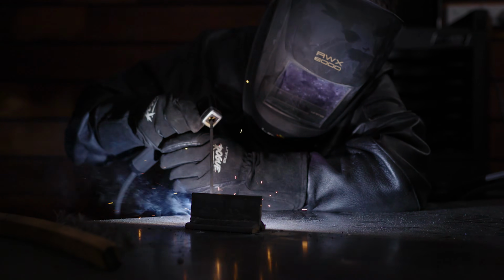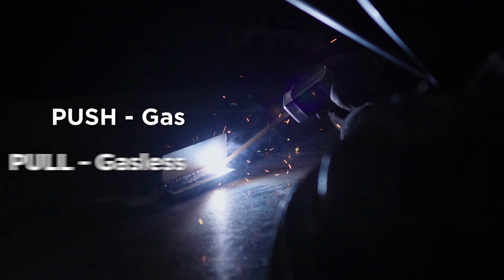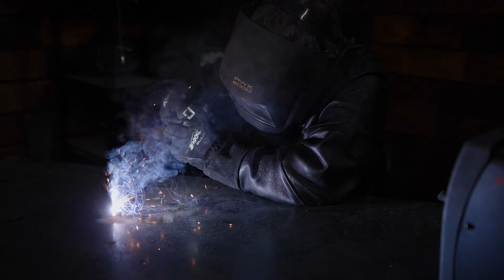How can you prevent or fix it? Adjust your settings and travel speed to suit your parent metal. Unimig machines all come with a settings guide to help you with this. Make sure you're using a proper welding technique, push for gas and pull for gasless. Also, check your torch angle. It should be at a 45-degree angle.